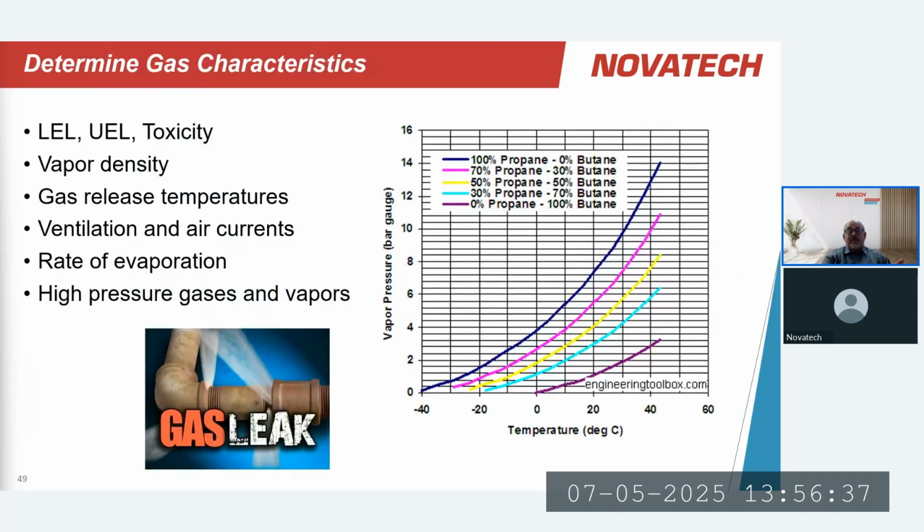You, of course, have to think about the gas. And back to the example I used earlier, Novatech, for example, often makes sample conditioning systems for customers in the refining and petrochem industry. And if I use that example of the sour gas that we talked about earlier, and I have a sample system in an enclosed box, the natural instinct would be, well, of course, it's flammable gas. I'm going to put an LEL gas detector in there.